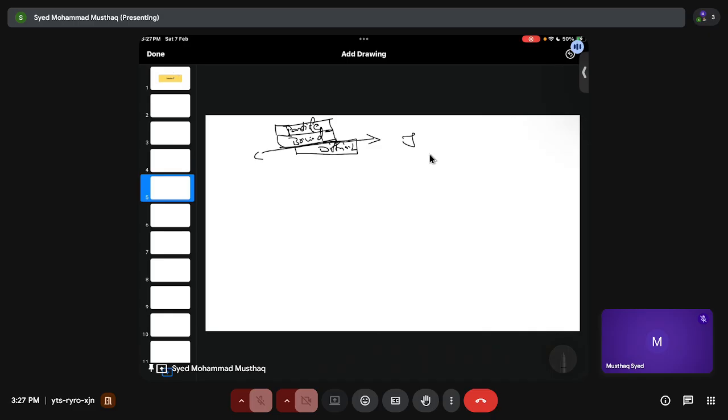And the potential at that layer is called the zeta potential. People even call it the plane of shear, because on that plane the shear is happening. It is happening like this, it's happening like this. On that plane it is shearing, and the potential of that plane is called the zeta potential. And for ideal coagulation, the potential at zeta should be zero.